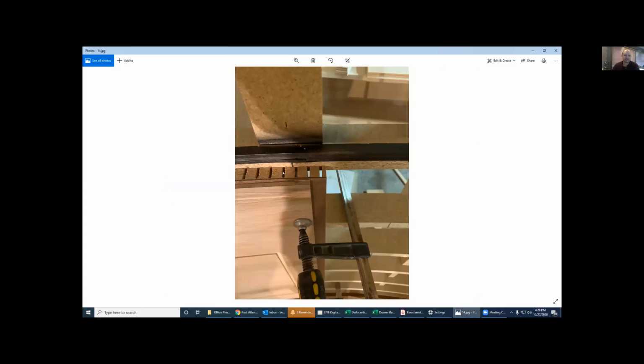This is our sandwich. We had a kerf core panel with a 1/4-inch veneer panel glued to the front of it, clamped to the radius. So when the glue dried, we held our shape. And then we pre-cut the grooves while the panels were laying flat on the router.